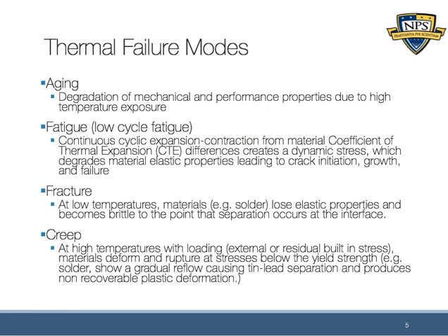Finally, creep. As opposed to low temperatures, this is more related to high temperatures, and specifically with loading being force, right? So at high temperatures with loading, and loading induces stress into the material. At these high temperatures with loading, there's a deformity of the material, so it causes the material to change its shape, and that can cause a rupture, and ultimately it exceeds the yield strength, and it causes it to actually break.